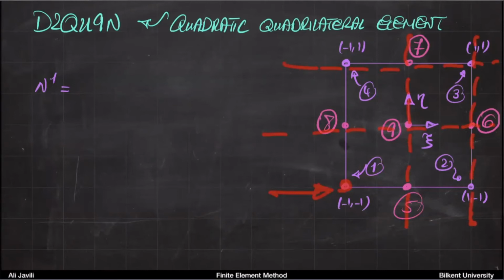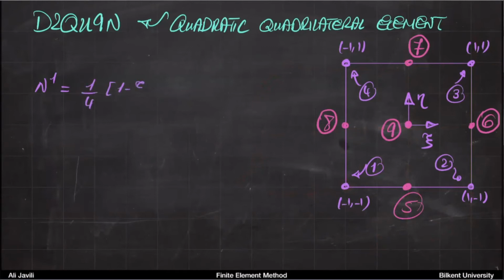So if you multiply the equations from those lines, you get something which relates to the shape function. So it would be 1 over 4, (1 minus xi) times xi times (1 minus eta) times eta. So again, you can see if, for instance, xi is 1 or xi is 0, so xi is 0 means this line.